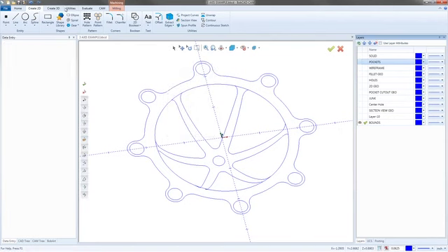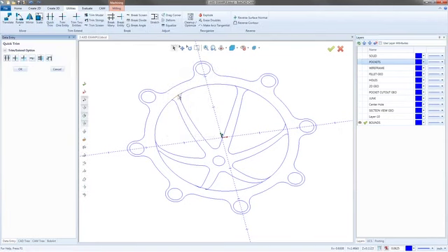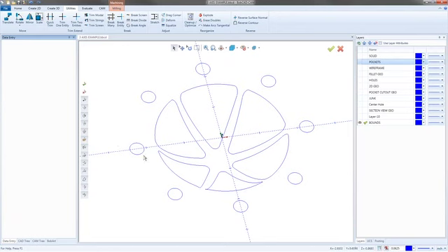So I'm going to go into my Utilities and then Quick Trim, and I'm going to start trimming away these things inside just like this, all the way around. I really didn't, oh no, I really didn't need it actually. I could have grabbed, no, I needed to grab both of them because I needed this whole surface. And this surface, when I picked it, gave me these lines back here. So I did need all of it. So that works. All right, cool. So that's all I need. I'm then going to delete all of this that I don't need. So this.